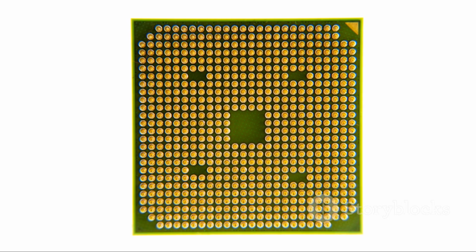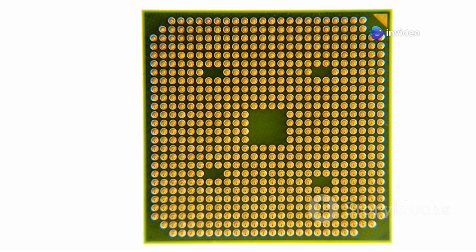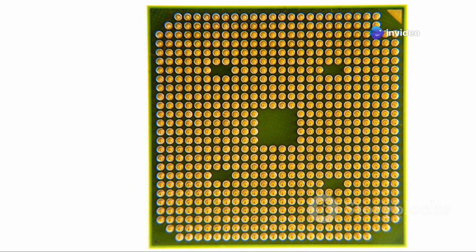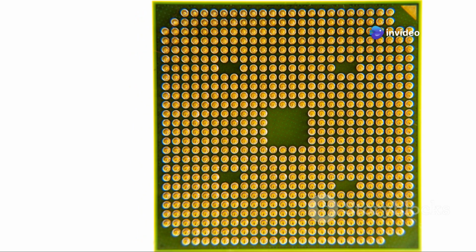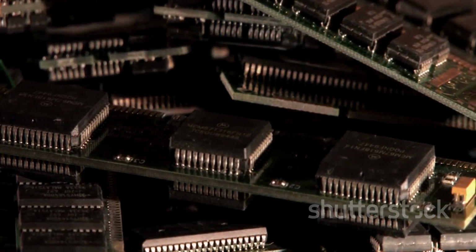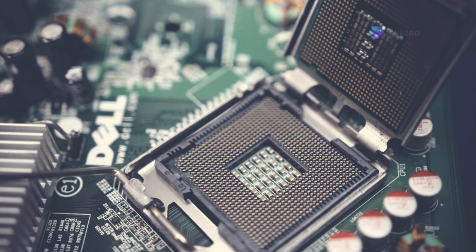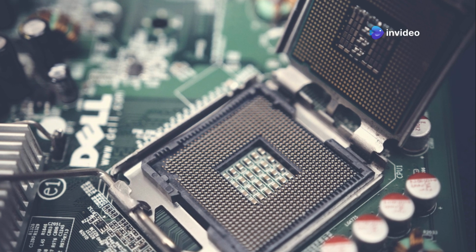Pins RST5.5, RST6.5, RST7.5, TRAP, INTR, and INTA are all related to interrupts. DMA allows certain devices to access memory directly without going through the microprocessor. This speeds up data transfer. The HOLD and HLDA pins are used for DMA operations.